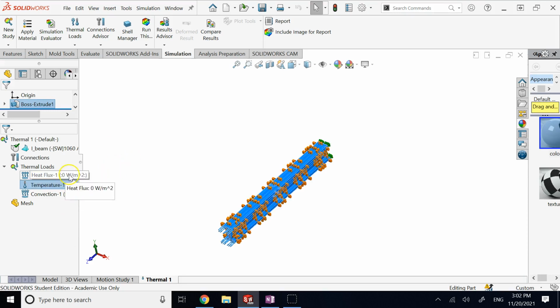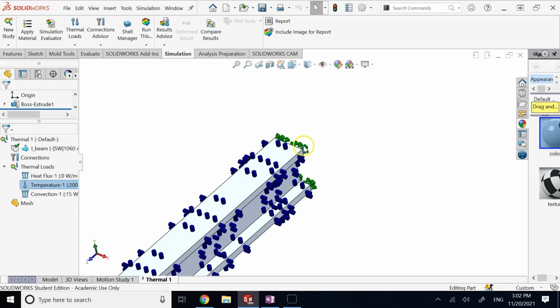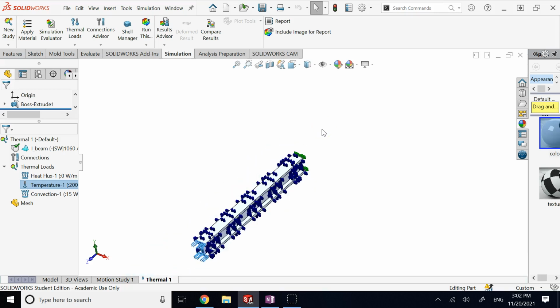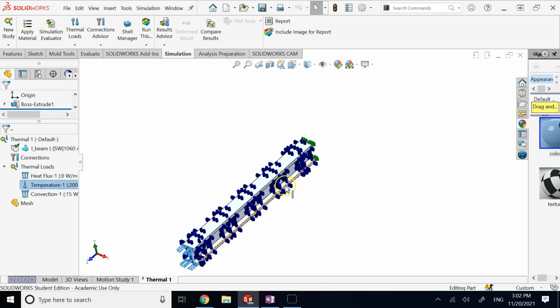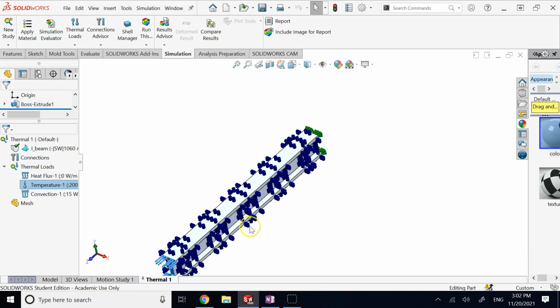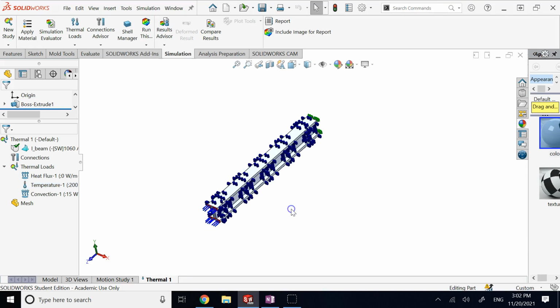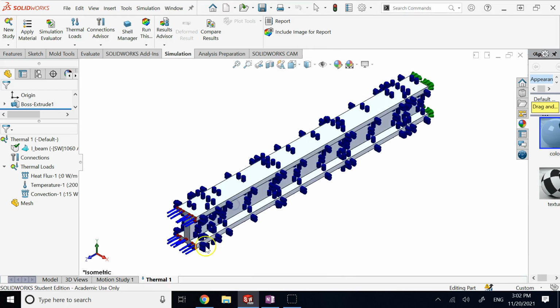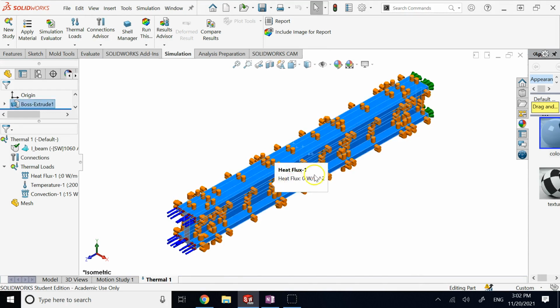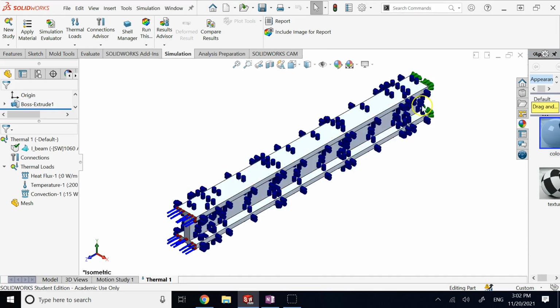So again, you see here, definitely the temperature is 473 Kelvin. Here on this side, the ambient temperature is 300 Kelvin. So your beam is definitely going to be hotter than the environment. No heat flux through any side face. So what you predict to happen is basically the heat from the left side, or front side, I'm sorry, starts the temperature to go up all the way to the right side. The temperature keeps going up, and as it does, then you're going to start losing heat from what?